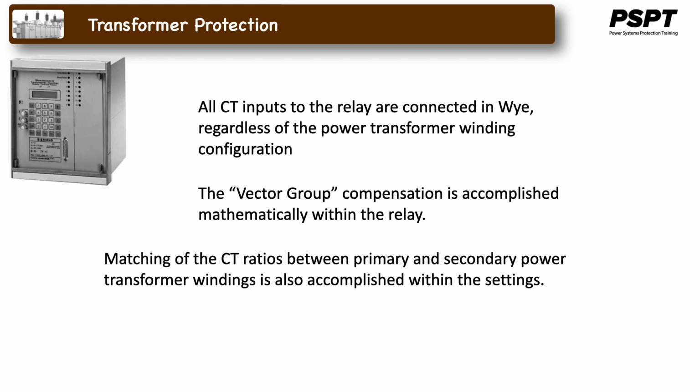In addition to the transformer protection, the 7UT513 is designed for application on bus differential protected zones. The relay has various techniques to recognize CT saturation. This relay also has 5 discrete binary inputs that are used to bring the status of external physical contacts into the relay. The relay contains an internal lithium battery that is used to maintain the state of alarm indications and a real-time clock and calendar through a DC supply interruption, if indeed it happens.